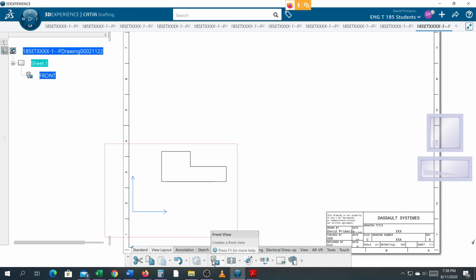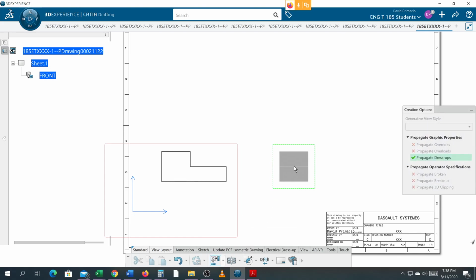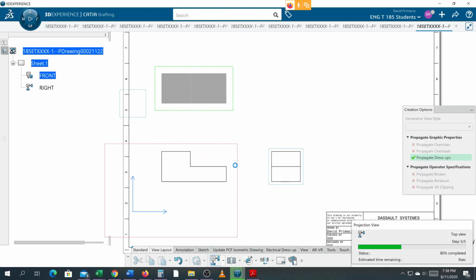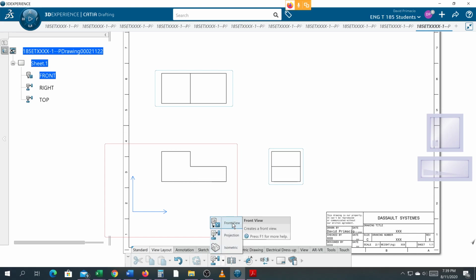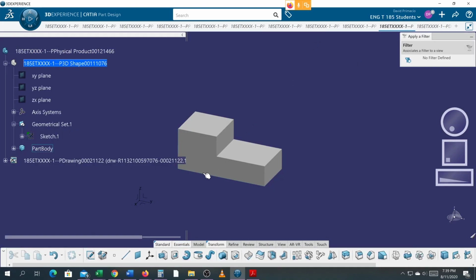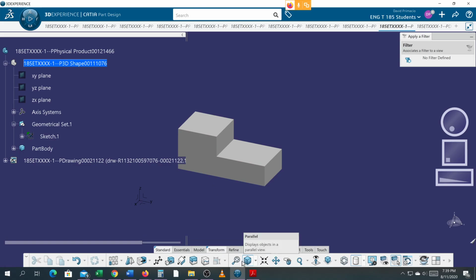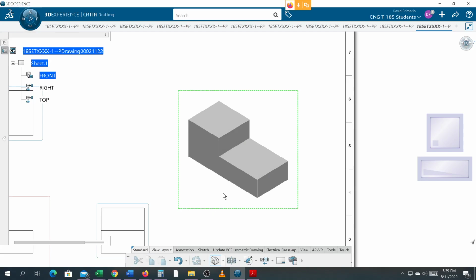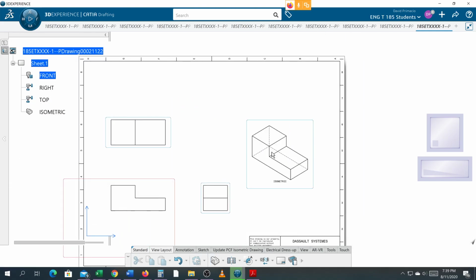I'll go back to the layout and lay out the principal view. So the principal view will be over here on this side. And I'll do another principal view over here. So we've done the front view, the principal views. Let's do an isometric view. So we select isometric view. Go back into space. You want to make sure you're in the ISO view. So when I click on this, it will build it on the ISO view. If it's clocked in a different orientation, it will assume you want that orientation. Okay, I'll click on that. It'll create the isometric view. I'll slide this view over here.